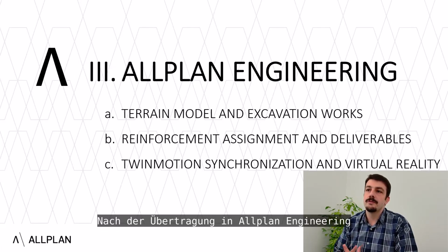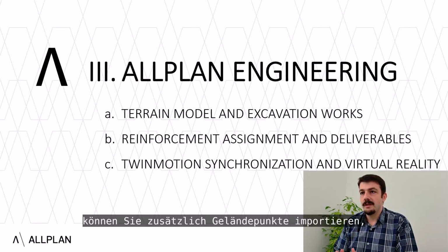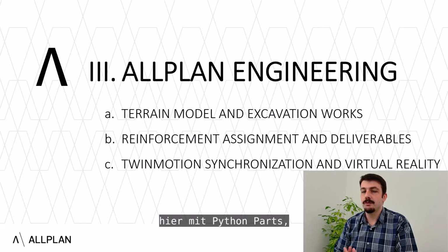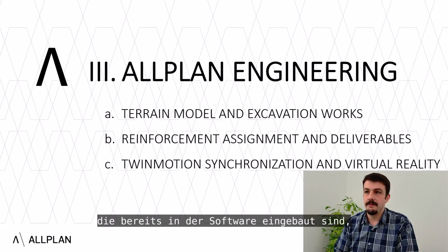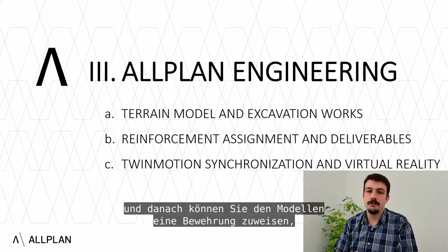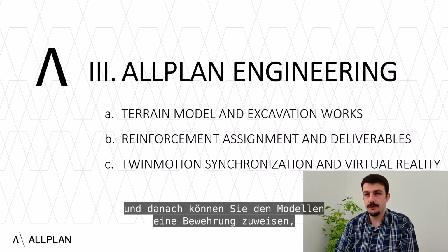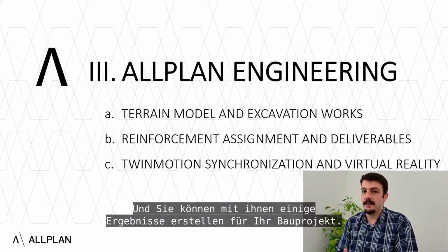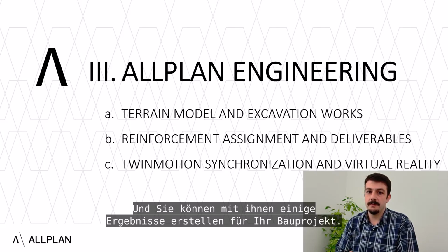And what you can do after transferring to the Allplan Engineering, you can additionally import a terrain point to create terrain model, and you can do some excavation works here with Python parts already built in the software. And after that, you can assign a reinforcement to the models, the structure members and girders, and even create with them some deliverables for your construction project.